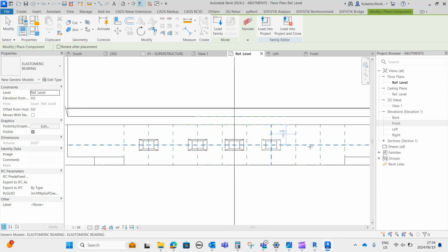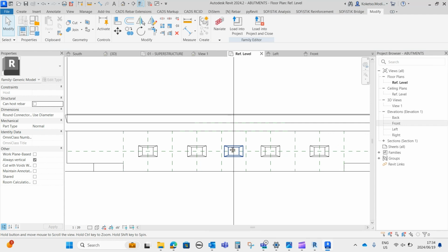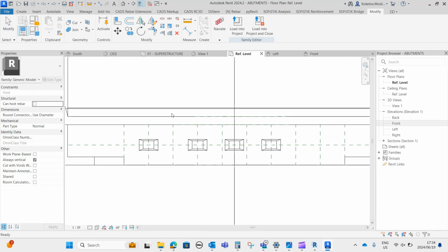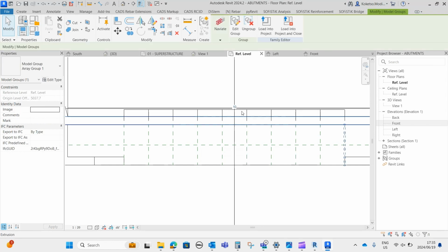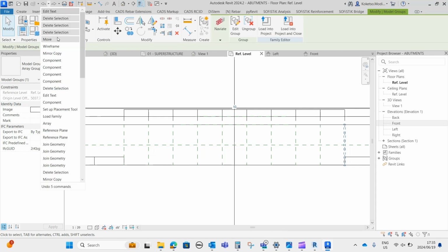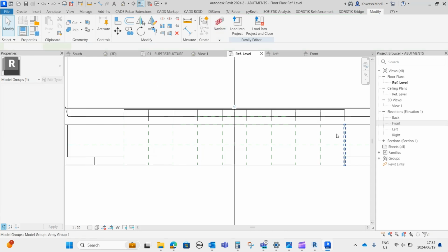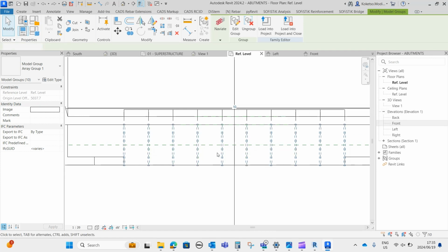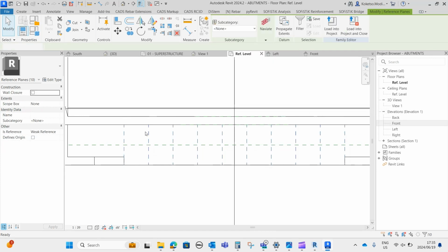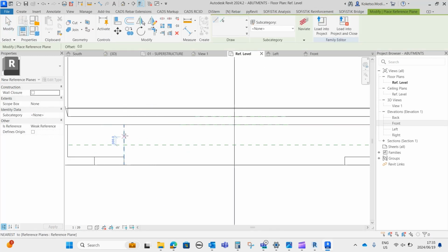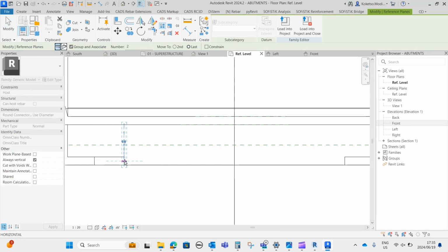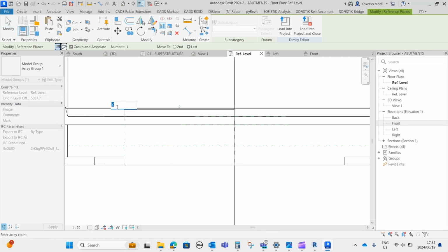So we're gonna skip one and then place them like this. Okay, let's just do this. Okay, let's just move our, you can just right click and then select all instances and then group them and then remove them. Let's just start over, say reference plane, place it like this, select it and say array, and then you're gonna array towards the middle point and then make it, I think we can just make it 10.